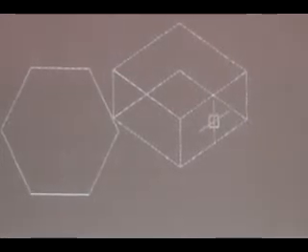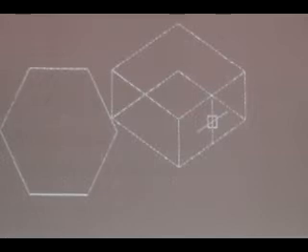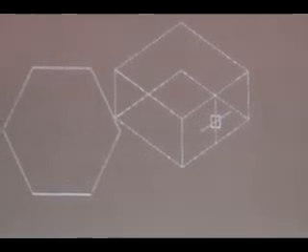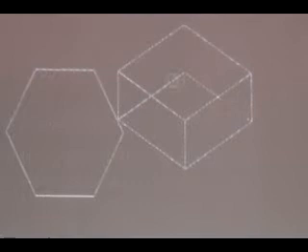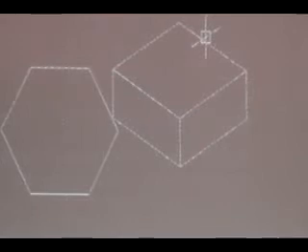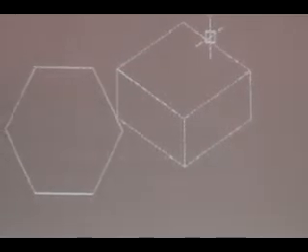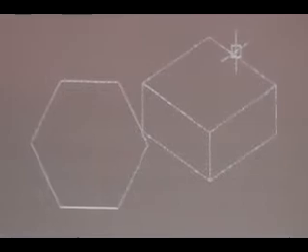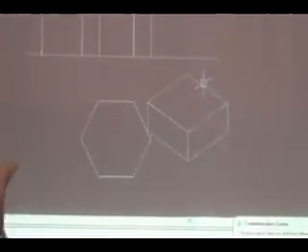Right. So to show your isometric, you don't show the hidden lines. Whichever portion you want to remove, I can erase it. So you can go for the erase command, I can erase this. Right. So this is your isometric. It's easier to draw the isometric views using computers. Extensively we will be studying this in your next semester, as practicals.